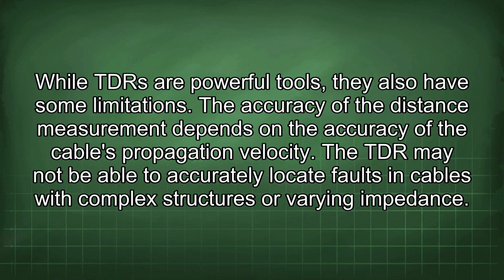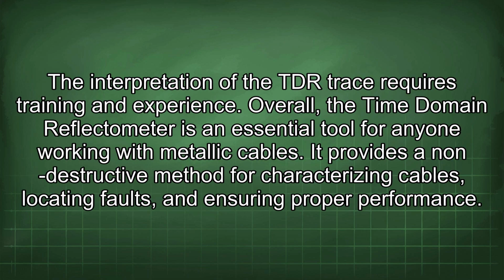While TDR are powerful tools, they also have some limitations. The accuracy of the distance measurement depends on the accuracy of the cable's propagation velocity. The TDR may not be able to accurately locate faults in cables with complex structures or varying impedance. The interpretation of the TDR trace requires training and experience. Overall, the Time Domain Reflectometer is an essential tool for anyone working with metallic cables. It provides a non-destructive method for characterizing cables, locating faults, and ensuring proper performance.